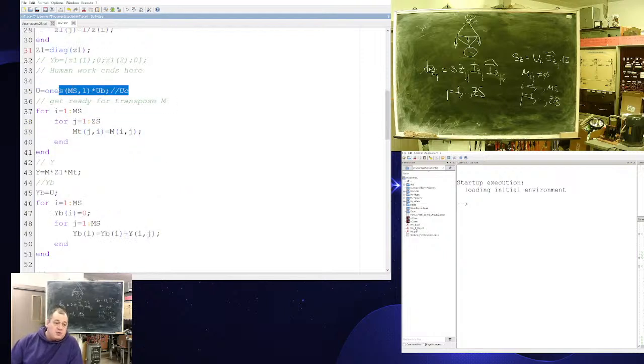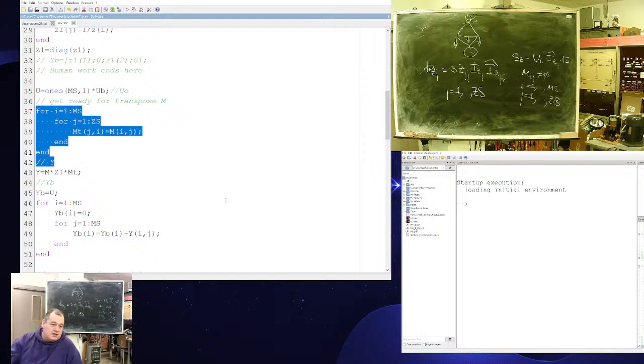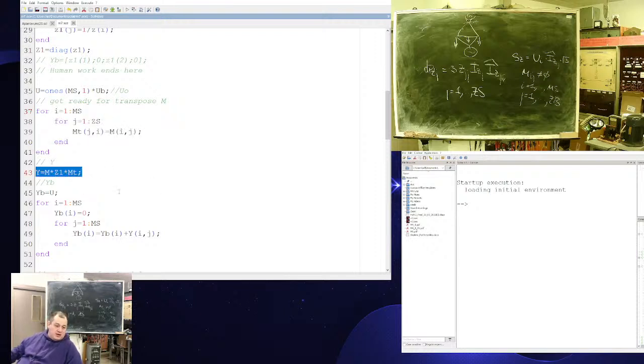Okay, what's next? This one. What's in this row? I assume that node voltages are not far from the base. So, if I start my sequential approximation process from something reasonably close to the solution, I will save time. This part, I need very simple. I need the transposed incidence matrix for this nodal admittance matrix.